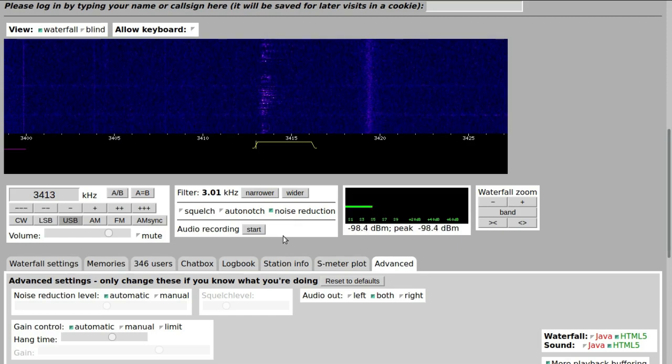It gets even worse as Shannon Volmet fades into the noise. At that point, there's just nothing. And you can't make something out of nothing. To mitigate those negative effects, I'll go to manual mode and reduce the aggressiveness of the LMS function.